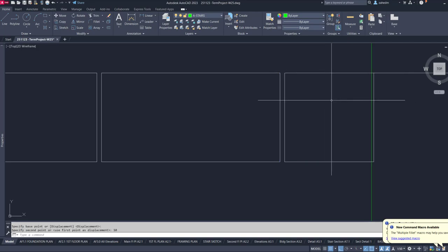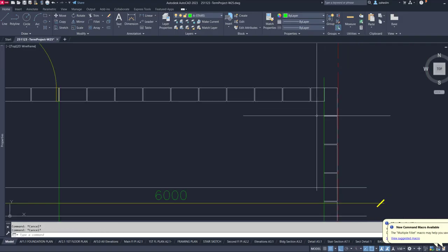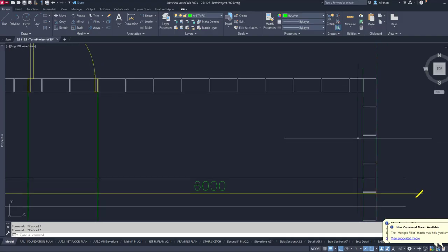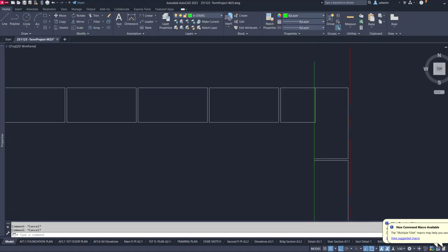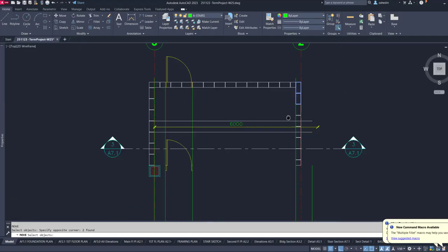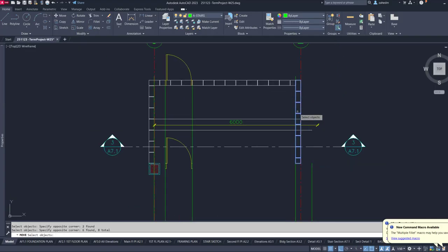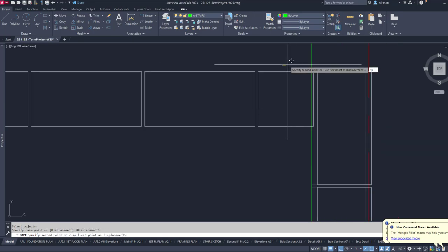What is really important is to make sure all these white lines are in the depth point, because you don't want them to print. That's a very, very tricky one, and you have to know that from the beginning. Okay, so what I would see here is the number 5200 did not count for the mortar joints. I'm going to move all these blocks to allow a little bit of mortar joints. So move them all 10 millimeters.